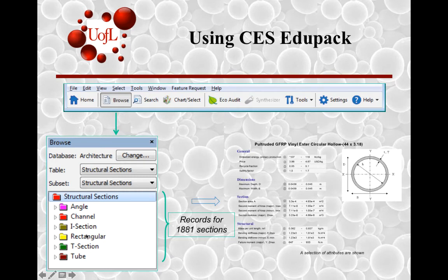If you click on any one particular material, for instance this tubular section, you will see that under the general category, you have the price range that these things exist in for this type of geometry, the safety factor required, the recycle fraction that exists, and the embodied energy. So now we are beginning to get into a new parameter that can be used as a design criterion, which is how much energy is consumed, in this particular case for primary production, that is for creating that material.